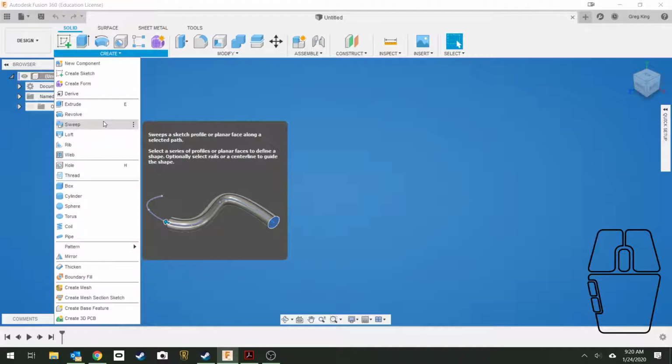This is a single line where the path starts at the center of the shape and is on a plane that is perpendicular to the plane that the original shape was on. I started with a plane like this, drew a shape, have a plane now it's perpendicular to that original plane, and I draw a path for that shape to go, and then the shape I made originally follows that path.